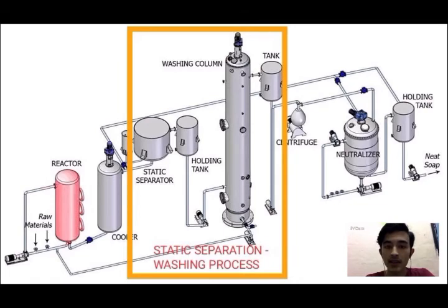The rate of productivity of glycerin is determined, and the rate at which fresh lye is added to the washing column is set to 25% to 55%. Glycerin is removed from the spent lye. Glycerin is almost infinitely soluble in brine, but at more than 35% glycerin, the lye no longer extracts glycerin effectively from soap. The soap is allowed to overflow from the top of the column. The lye is pumped away from the bottom at a controlled rate and added to the reactor.